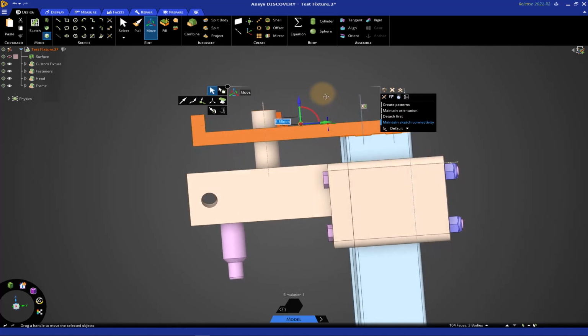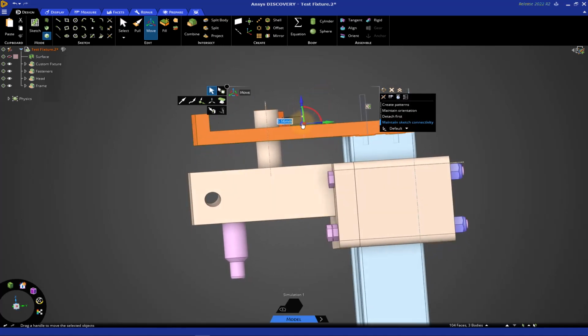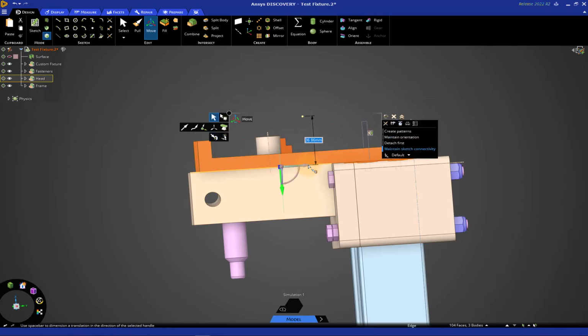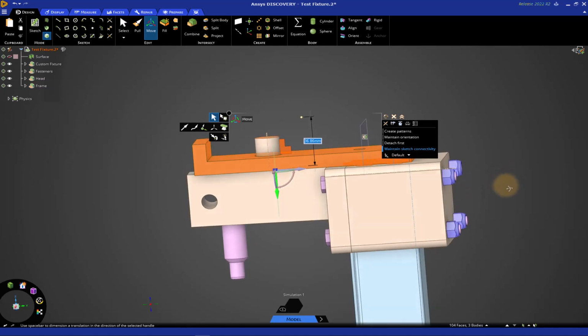Now I might want to snap it, and I could either drag the move handle down to here, or there's actually a tool guide that lets me pick something for the move anchor to attach to. Now I could go ahead and either use an up to command or enter a value to snap it down to the height, and it's maintained that interface all in one action.